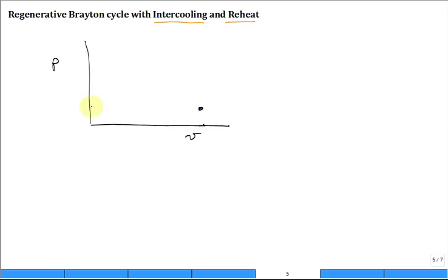And if I want to go from this pressure to that pressure, a specified pressure ratio, I compress it. Typically, I compress it with s equal to a constant, isentropically, and I'm up there. This is an open system, so we're flowing through a control volume.